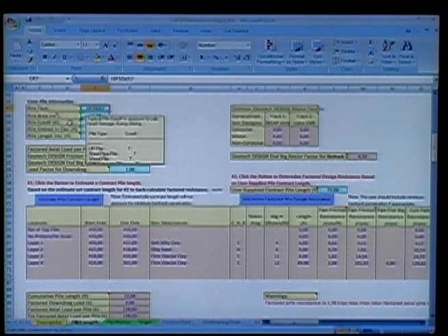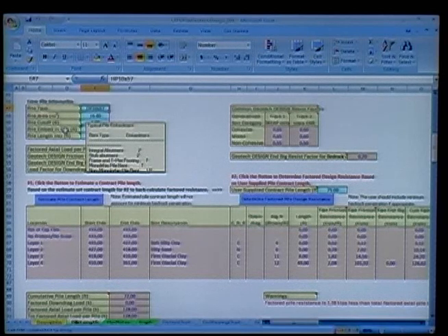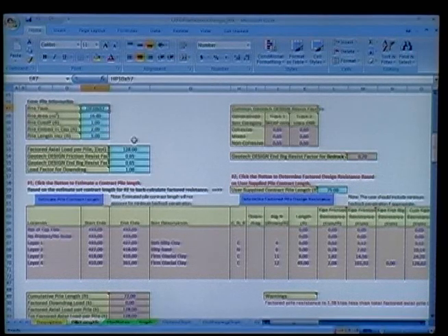Pile cutoff is used. Once again, it's the zoom scale that's, I think, screwing this up. But I give you the basic cutoff for the different pile types. I give you the embedments we use on our different types of footings, whether integral, stub, or frame, whatever. I give you the increments we usually round to for the different types of piles. You can enter all that in, and that's all used in determining the contract length. You put in the factored axial load like we've been talking, a nice little equation, the gamma Q. Throw that in, 128 kips in this case.